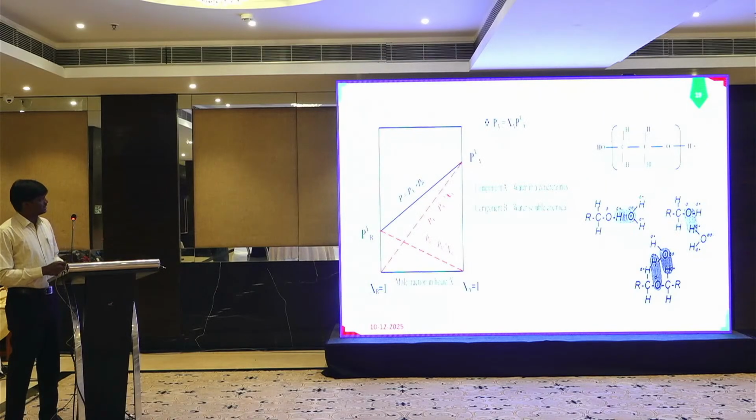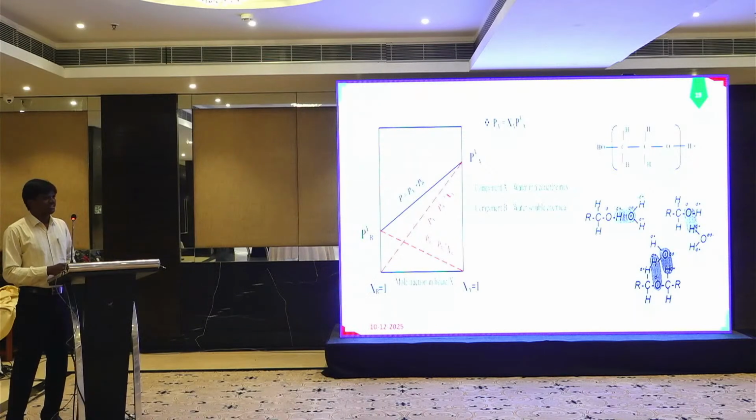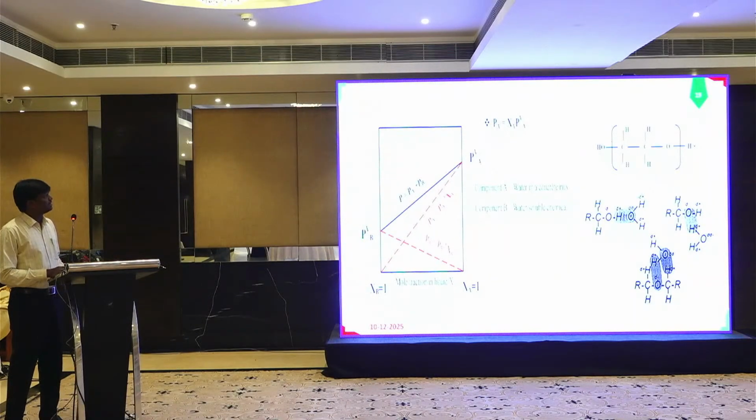And this is how PEG reacts with the water. When it reacts with the water, it forms a hydrogen bond, and when the heat of hydration increases, that bond breaks and the water is given to the cement.